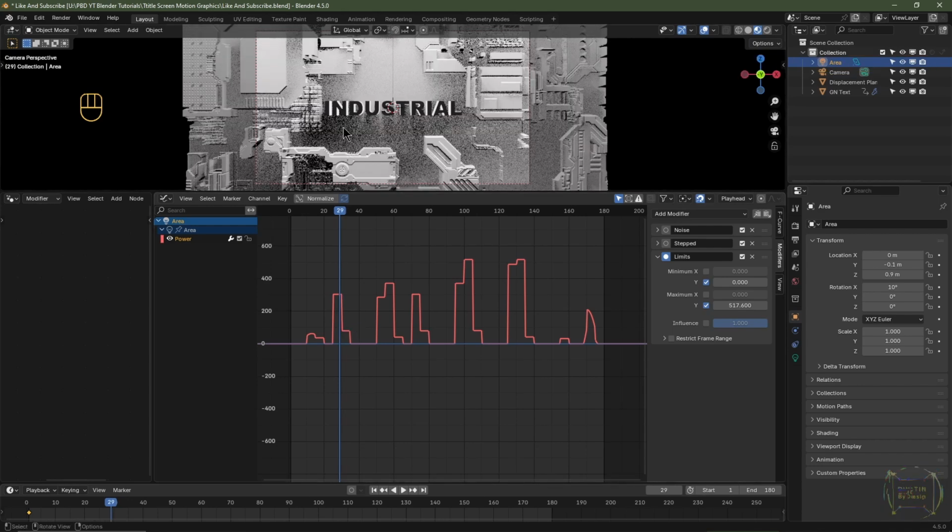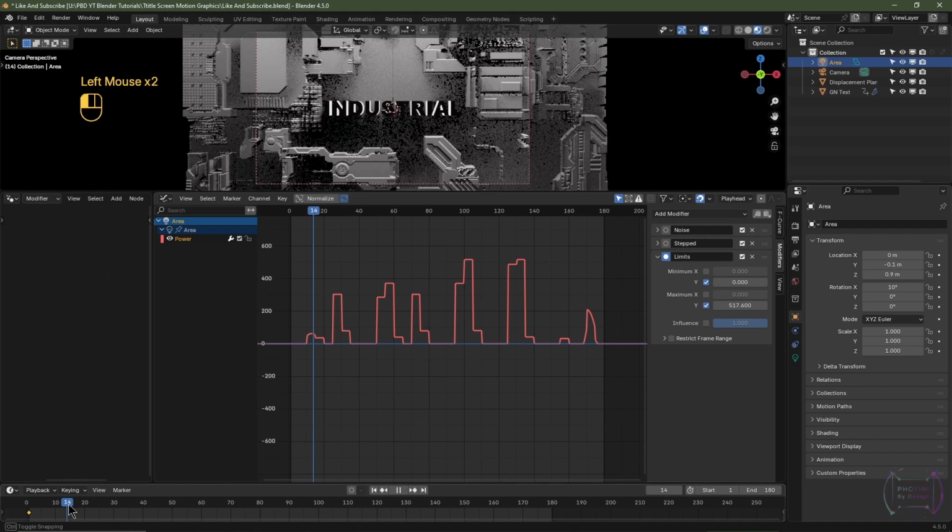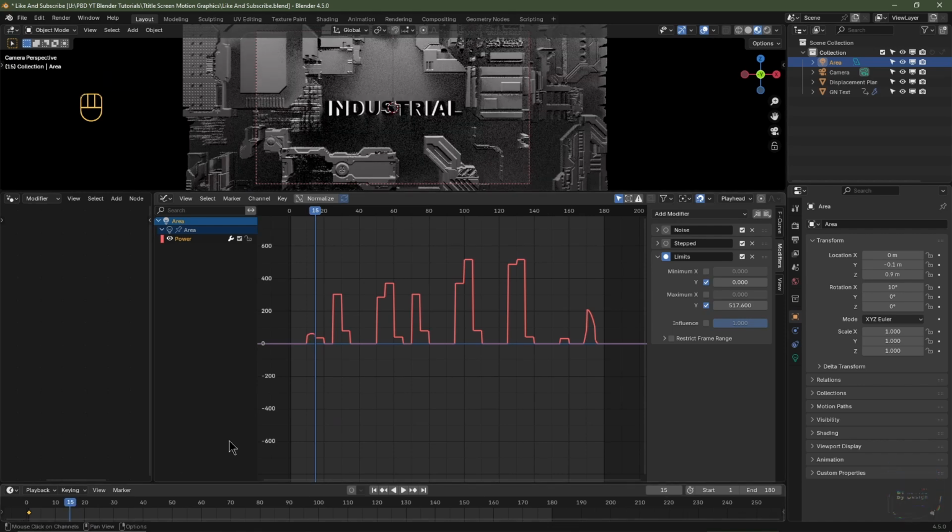As you can see, the area light is kicking in before the text object is revealed, and it's 100% revealed at frame 15. So we need to ensure that the start value only happens after frame 15. Maybe we could start it on frame 20 or even frame 30.